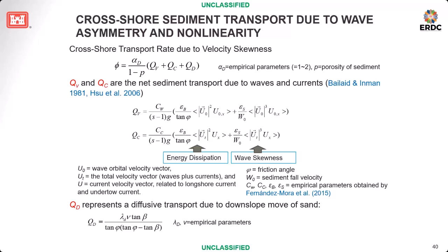So if you use a transect model and only look at a short period of time, you may have good results. But if you use a transect model to simulate a year long, including fair weather, seasonal, and the storm, you won't have a consistent natural signal in your shoreline change.